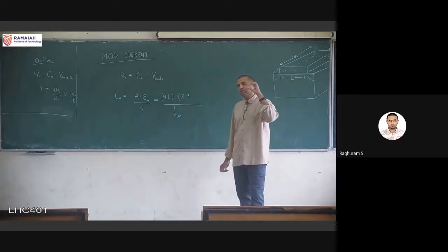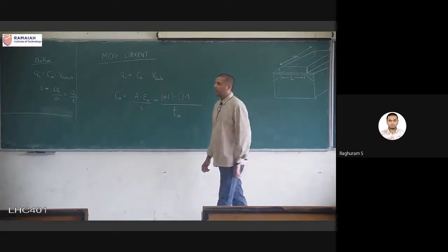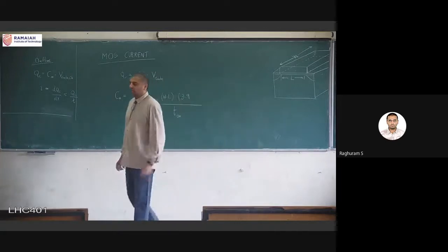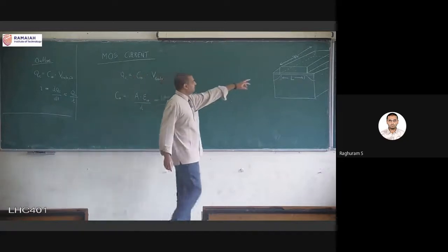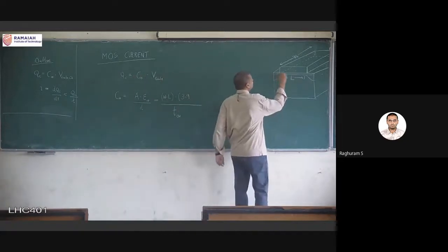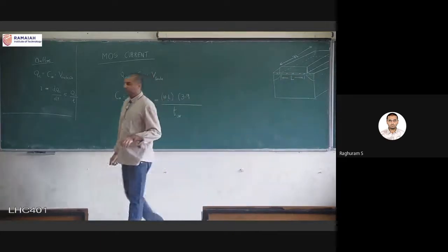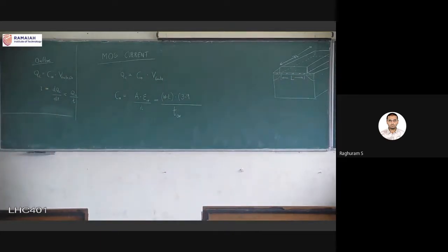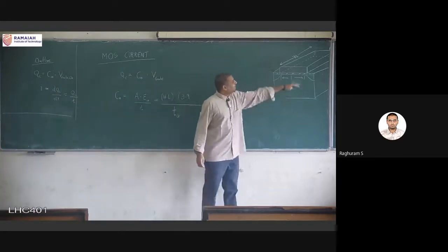It started shrinking almost to the size of 2 nanometers. When it went to that level, what started happening was the leakage current. We said that the silicon dioxide here is responsible for the insulation of the gate terminal. That is true. But when the thickness was so low, it became very difficult to control current in this direction.